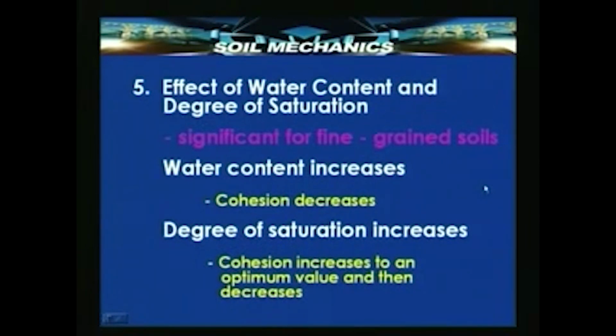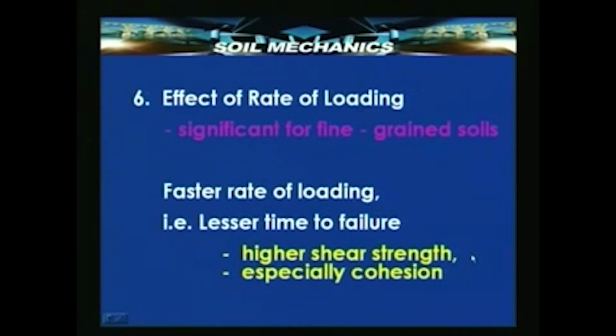Water content and degree of saturation also play an important role. When the water content increases, cohesion decreases. When the degree of saturation increases also, the cohesion increases to an optimum value and then decreases.